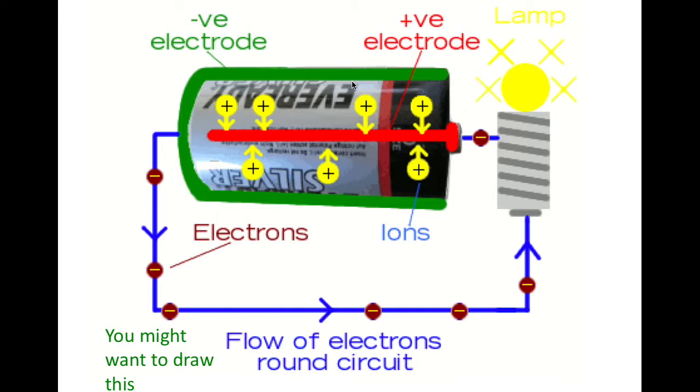It's important to note that the electrodes in a battery are always made from two different materials, so never both from the same metal. This is the key to how and why a battery works. One of the materials has an affinity to give up electrons, and the other likes to receive them. If both electrodes were made from the same material, this transfer of electrons would not happen, and no current would flow. So the positive and negative electrodes are separated by a chemical electrolyte. It can be liquid, but in an ordinary battery, it is more likely to be a dry powder.